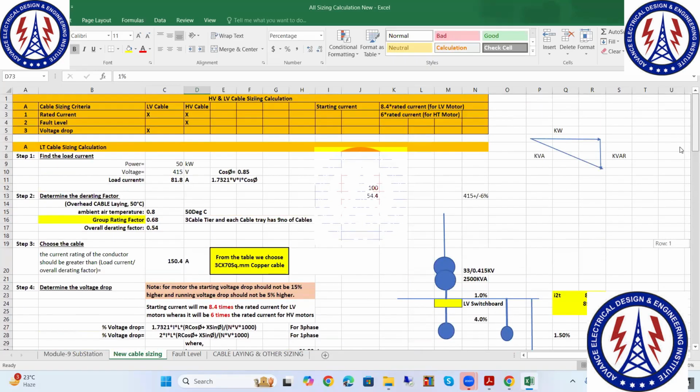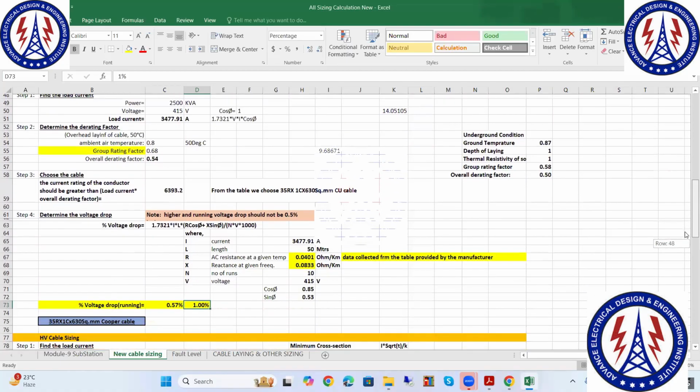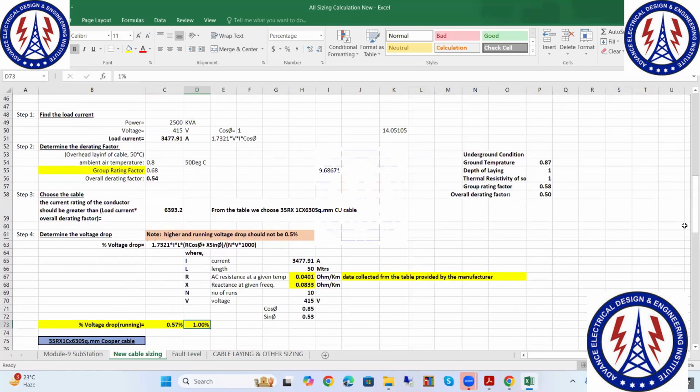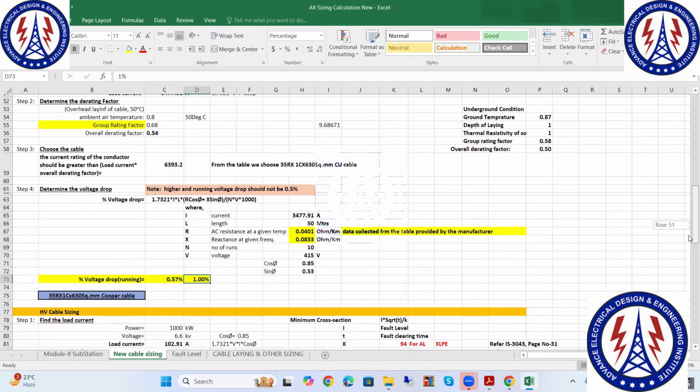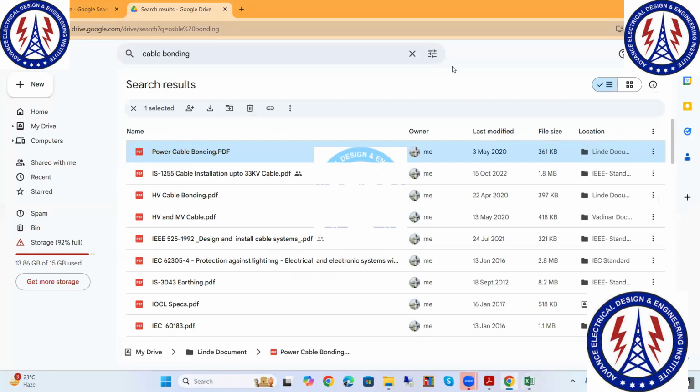Sir, regarding the transformer cable sizing, if we go for more number of runs to overcome the situation, how will the connections be? Should we discuss with the vendor? No, why discuss with the vendor? Go for trefoil, because a transformer is an unbalanced load. Trefoil, RYB like this.